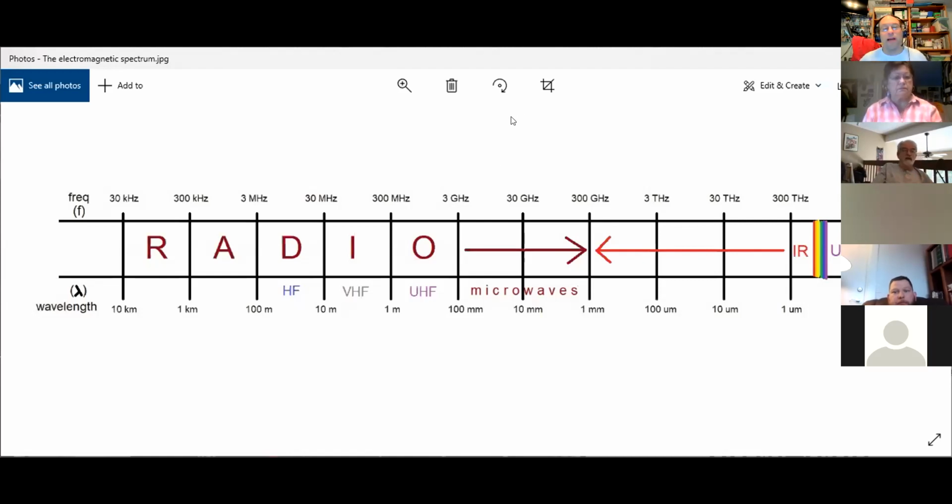A TV signal is 6 megahertz, but now look between 300 megahertz and 3 gigahertz. How much room do we have there? Tons. We have 2,700 megahertz. A 6 megahertz signal, it's perfectly logical to put it there. So that's why we're only allowed to run fast scan TV on UHF bands and higher, because they take up a lot of room. That's why our old TVs had like 12 channels VHF and 100 UHF. That's exactly right, because there was a lot more room in UHF.